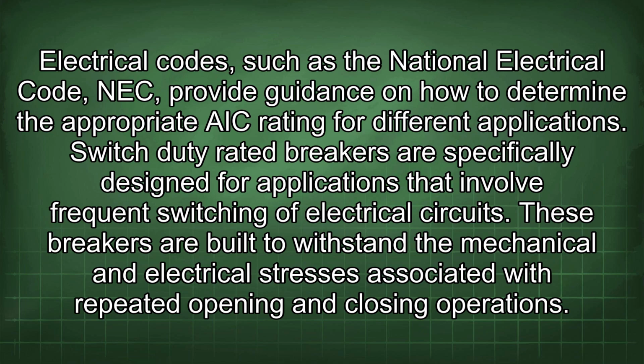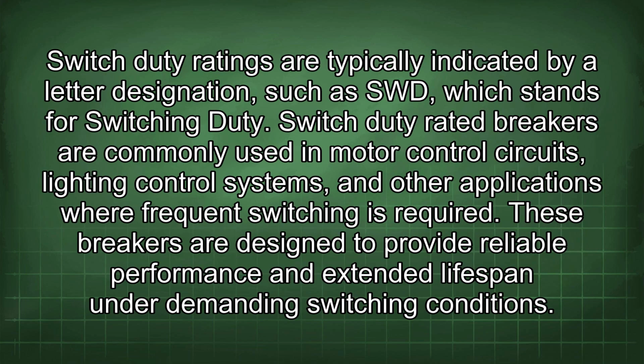Switch-duty rated breakers are specifically designed for applications that involve frequent switching of electrical circuits. These breakers are built to withstand the mechanical and electrical stresses associated with repeated opening and closing operations. Switch-duty ratings are typically indicated by a lettered designation such as SWD, which stands for switching duty. Switch-duty rated breakers are commonly used in motor control circuits, lighting control systems, and other applications where frequent switching is required. These breakers are designed to provide reliable performance and extended lifespan under demanding switching conditions.